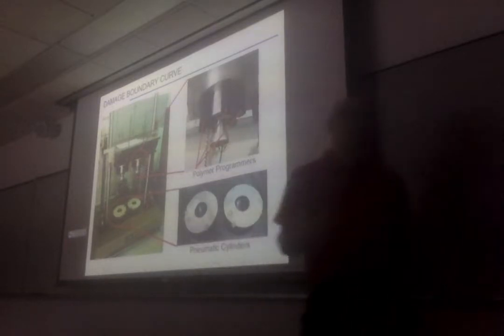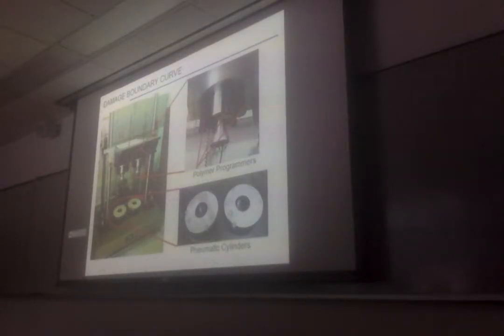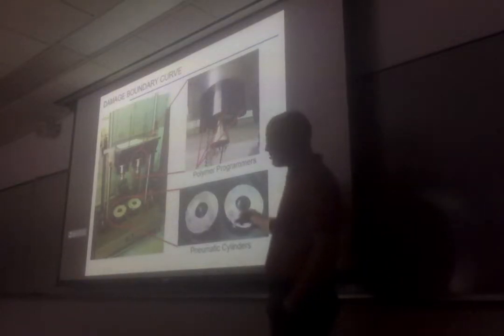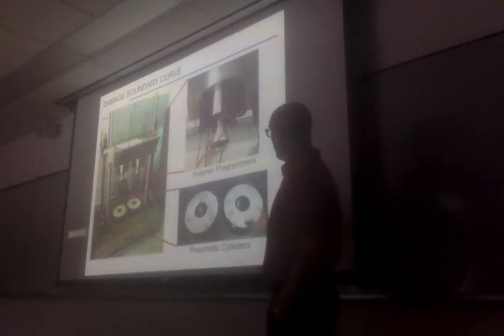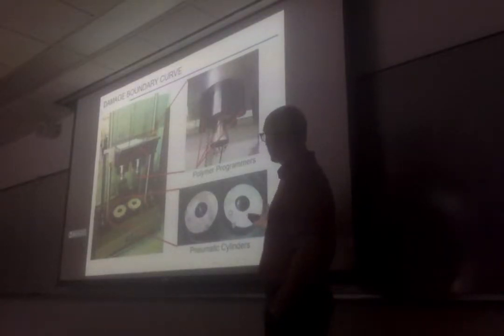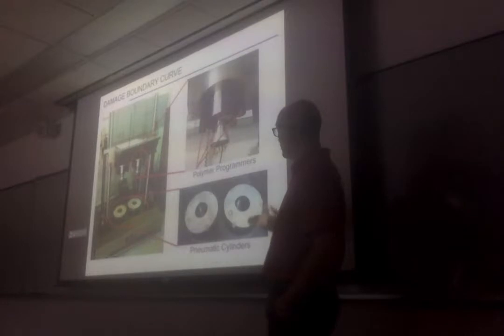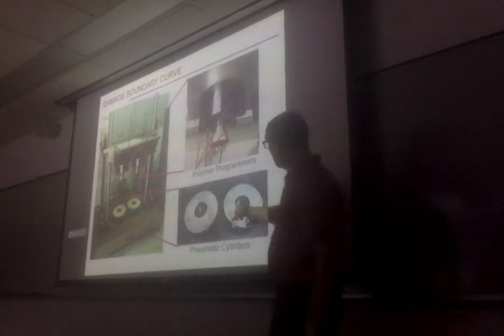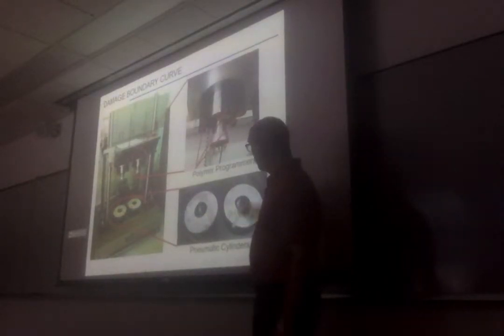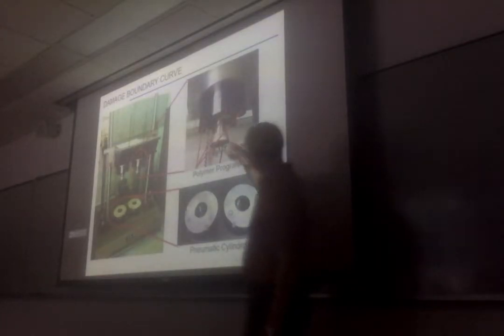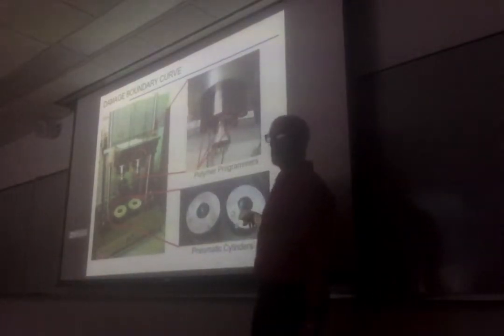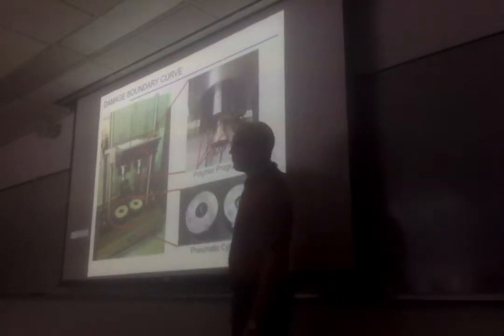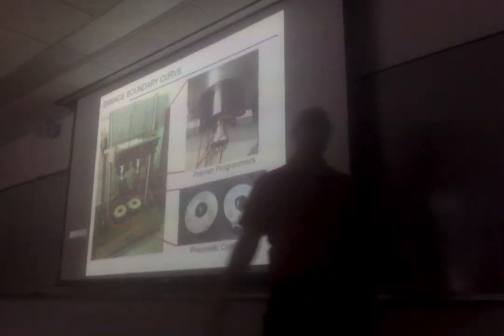Now, the second series of tests requires those trapezoidal impacts. To create that, we use pneumatic cylinders. These can be pressurized at different pressures, obviously. The first few times you do that, it kind of freaks you out a little bit when you pressurize it, because those two pistons go back up, poop, okay? And they make that funny sound. And so when you drop the table after that, the impact occurs when the plunger hits the piston, not when the programmer hits the felt pad. So you create different types of impacts.